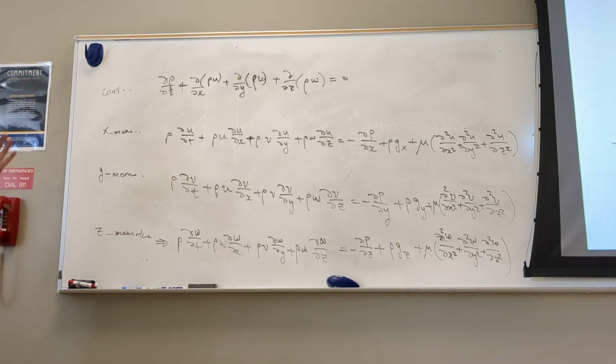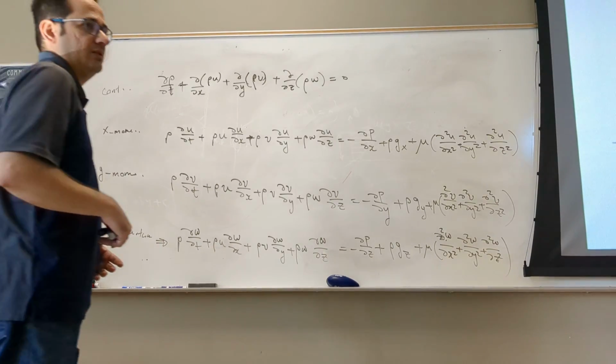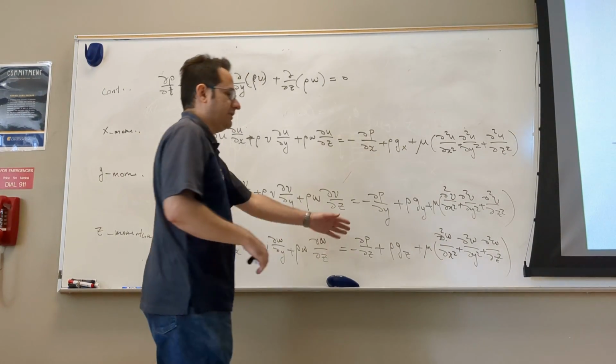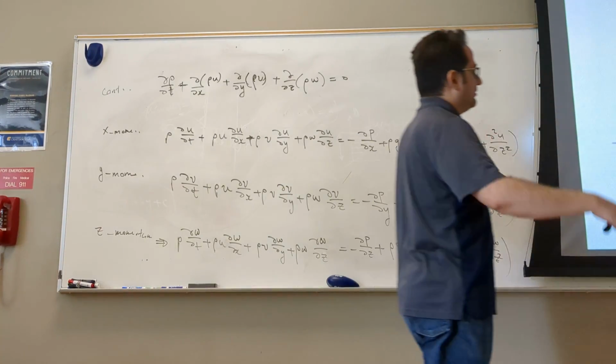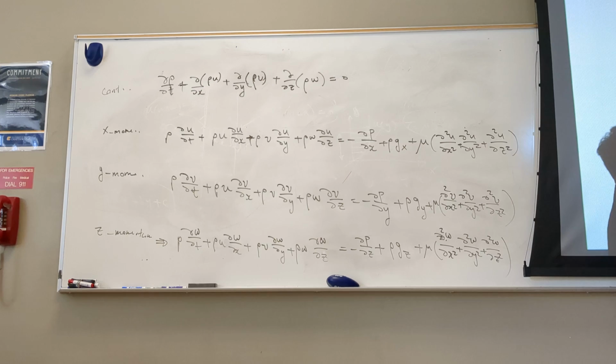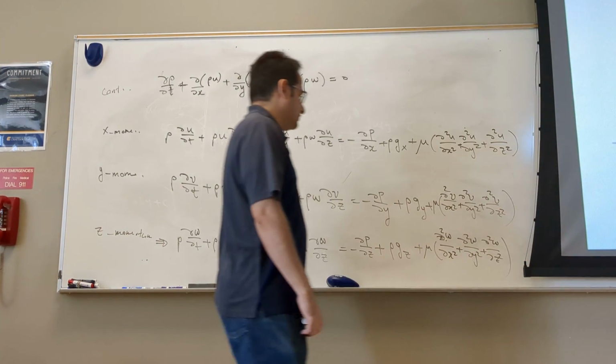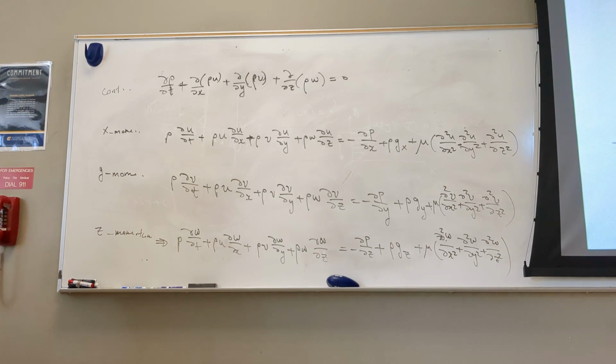But look, the energy equation, we are only interested in it if we have a huge difference in temperature or a huge amount of turbine work or things like that. Then we have to solve energy. But here, we assume that everywhere the temperature is ambient temperature and the pressure is exposed to the atmosphere, so the pressure is the same everywhere. So in this problem, the energy equation is not something you're interested in solving. You could, but it's just a waste of time.